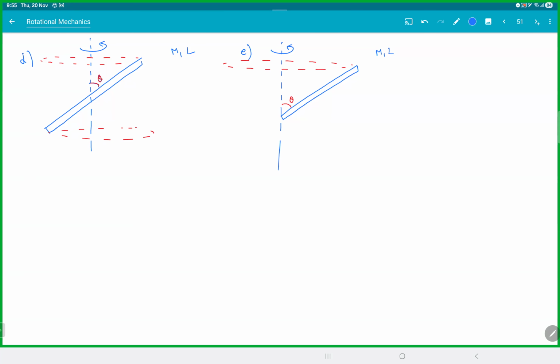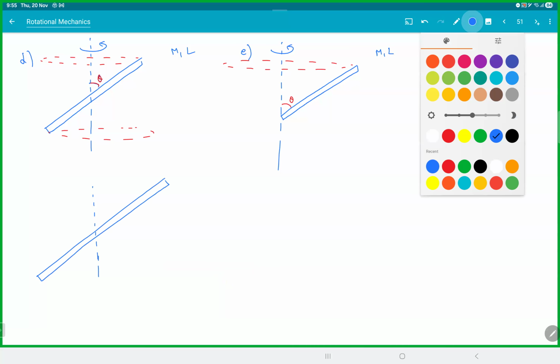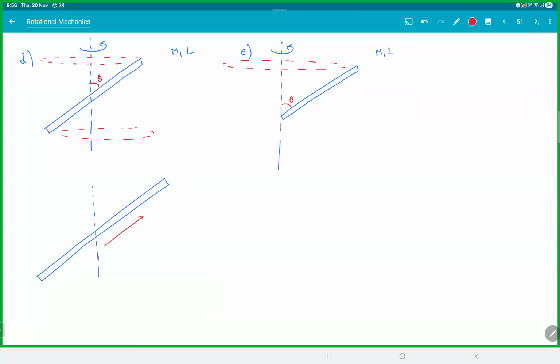See? So how do we choose an element? Be careful, x should always be taken along the rod, because when you're choosing an element, dx must be in the direction of x only. You can't take x like this and you can't take dx like this. You can't have two different directions. So let the distance be x. So this piece is still dx.